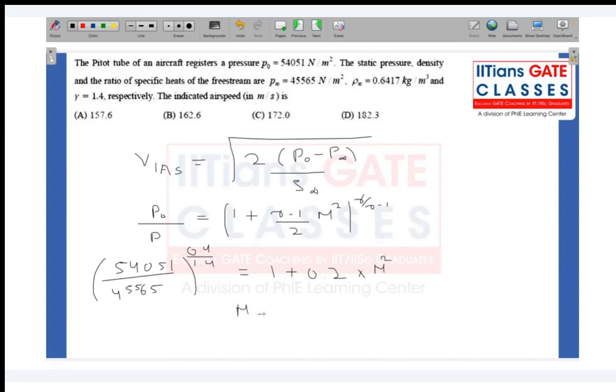0.5, which is greater than 0.3. So it's a compressible scenario. It's a compressible kind of scenario. So if you were to use this to find the velocity, it would give you errors. All right. So now, since we have the Mach number, you can actually find the velocity from the Mach number.